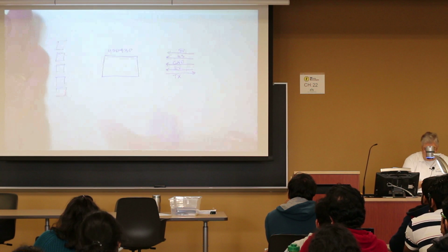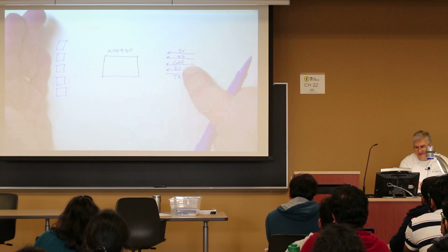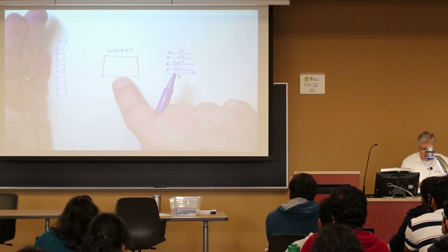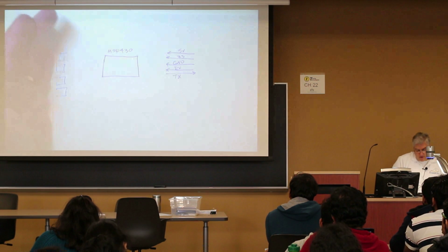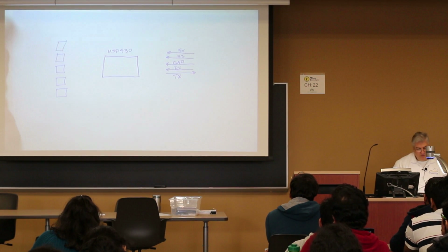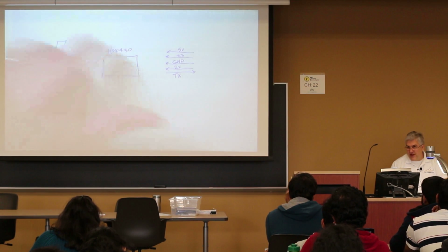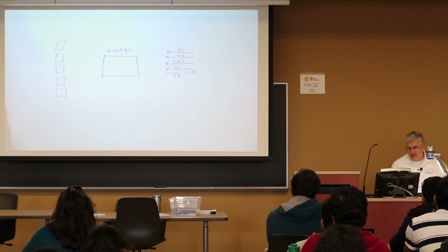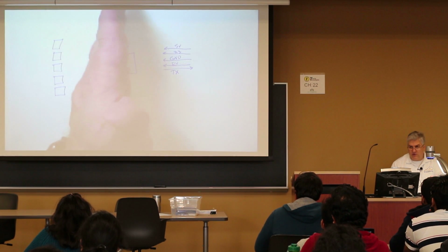Oh, we don't have a battery over here. Don't we need a battery over here? Well, that's what these are, right? MSP430. Do we need a crystal? Not really, because remember, it's built into this. What else do we need? Do we need memory? Probably just use the memory that's on there, right? Which means we have to have enough memory on there. And then we had said 5 sensors. How are these sensors communicating with this?